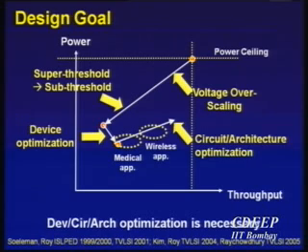And then some of the wireless applications would fall into such categories too. And then finally, going back to Maryam's question, should I really optimize my devices if I want to go back and forth? The answer is, of course, no. If you really want to go back and forth between superthreshold and subthreshold operation, depending on your load conditions, then of course your devices cannot be optimized. They should still be the standard superthreshold devices.